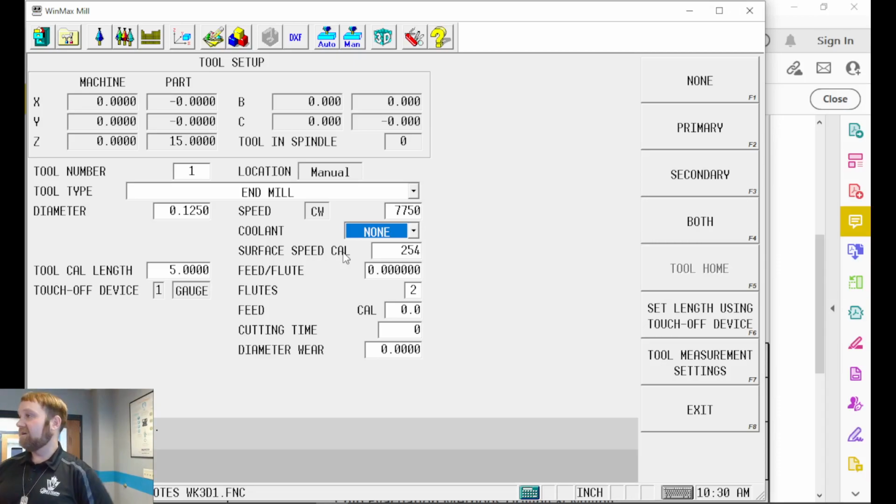So when you're in industry and you've got an employer that says, well, that 8,000 RPM spindle's $5,000 cheaper than the 15K, make sure you remind them, hey, we cut a lot of materials, and we've got to back off all of our tooling because the machine doesn't have the spindle speed to run the tooling at the RPM it's recommended. If we could run that RPM, we could speed up our feed rates. We get more work done. You see the value?